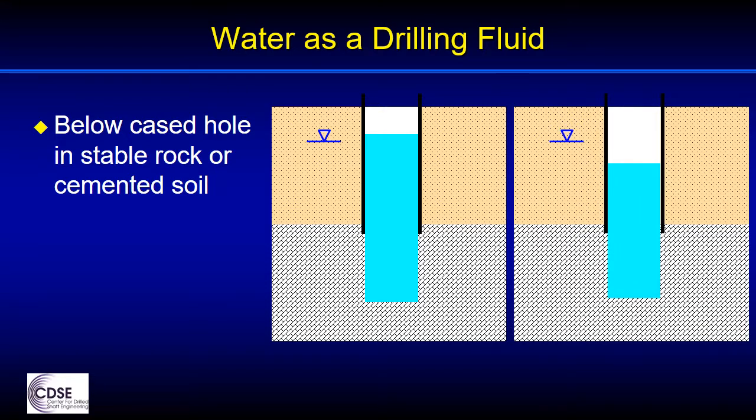If we don't add water and keep a positive head, an inflow of water occurs around the bottom of the casing, then this inflow can create a void on the outside of the casing above the rock surface if fines are washed into the rock socket. A noticeable quantity of overburden soils coming out of the rock socket excavation could be a telltale sign that inflow may be occurring. So we don't want this condition.